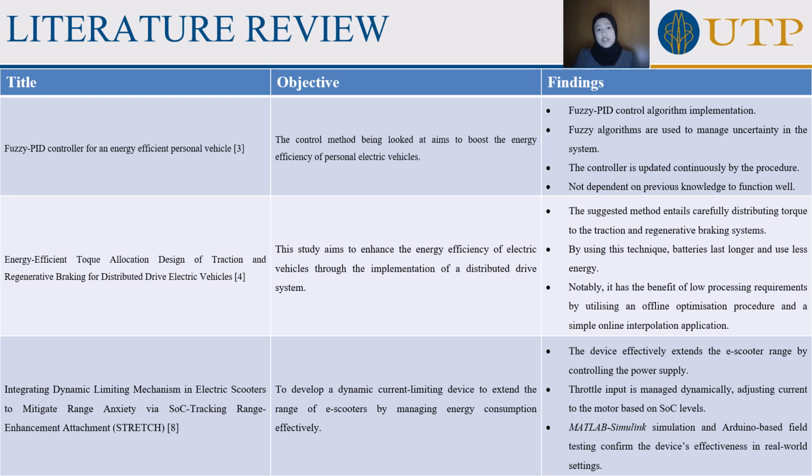Next, distributed drive systems, where energy waste is reduced by optimizing torque distribution. And lastly, dynamic limiting algorithms, which control throttle to extend battery range. However, dynamic throttle adjustment based on SoC remains under explored. So this project builds on these studies by proposing an algorithm for SoC-based throttle control.